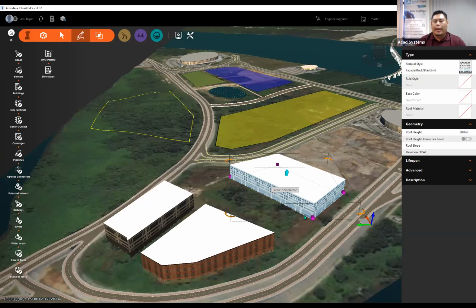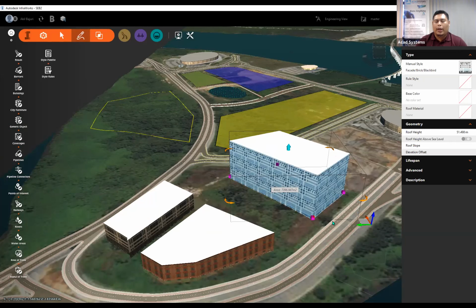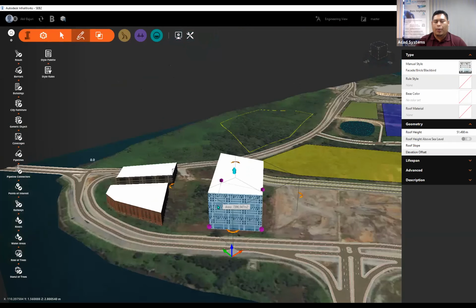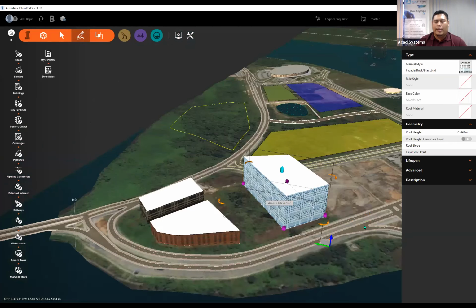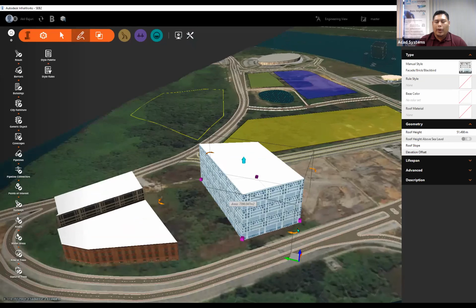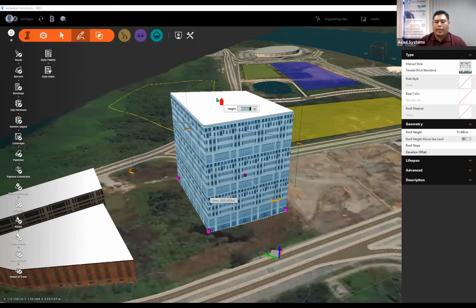When you want to plan, you're going to use this as your site analysis tool, so it will help you define things. Let's say you want to propose a building with a certain height. If you are proposing this building with certain heights, you will see what the environmental impacts on the building are: what areas it blocks, what areas it shades from the sun rays, and so on. And if you want to modify the positioning, you can always move this away, and it will help you update it. Let's say you want to make it a bit smaller than before, so it's very handy. And you can increase the levels as well.